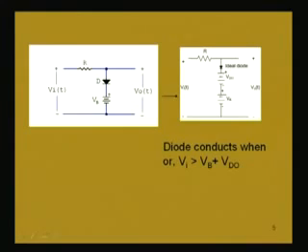plus Vd naught. If you find the potential at this point with respect to ground, what will it be? This Vb is already there. So, Vb, and again this is the diode drop. So, minus-plus in series, totaling up to Vb plus Vd naught. So, the potential at P must be higher than Vb plus Vd naught.